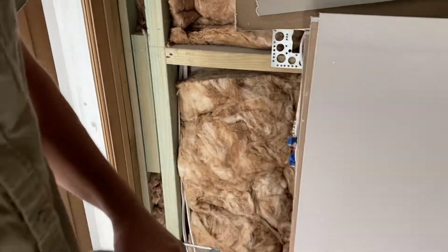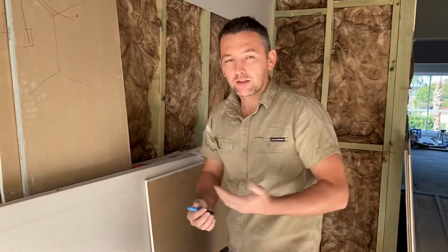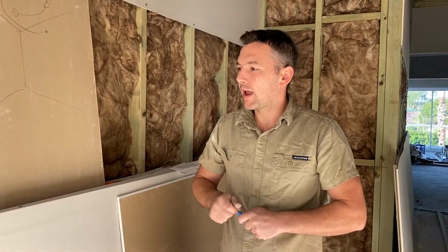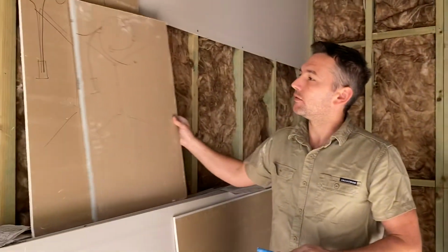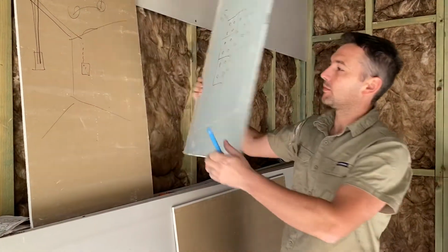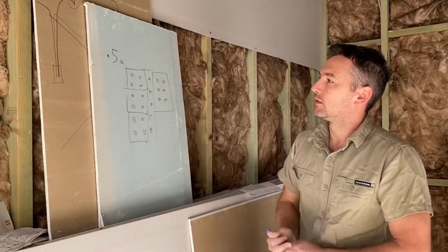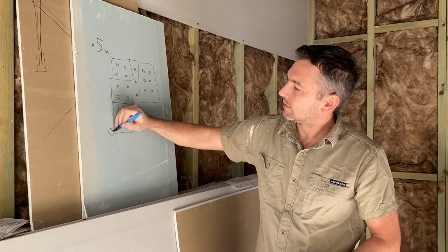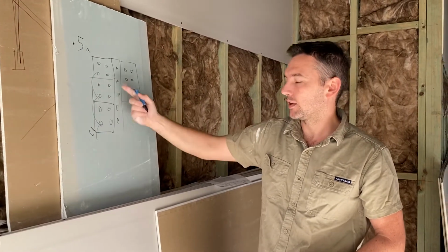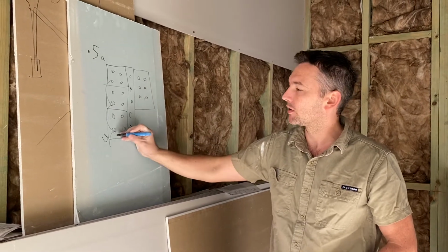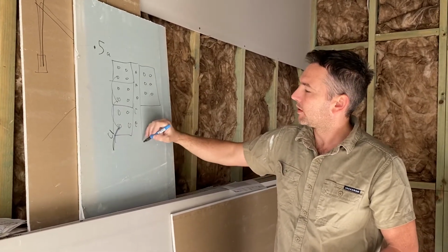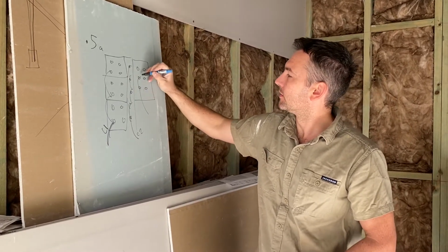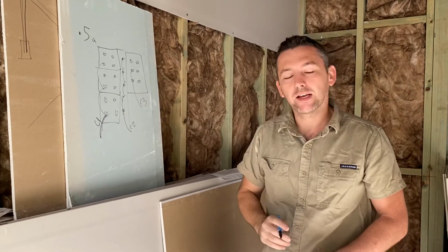All right, so you can use 2 different methods. Make a choice either way, so that it's consistent throughout the house, and plan out your loads appropriately, so you have the right amount of circuits per lights. So we said before we have at most 20 lights on that one circuit. So here's circuit 1, might plan circuit 2, and then have another circuit for a lounge.